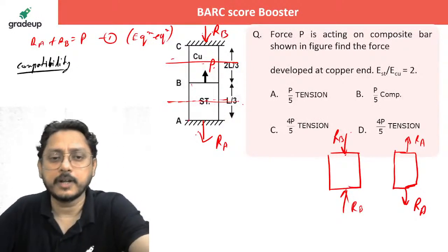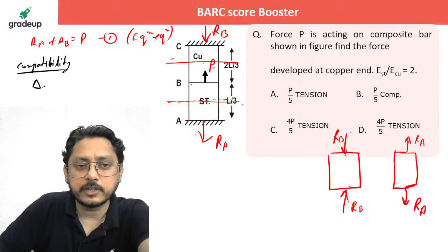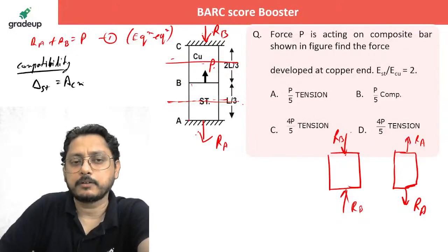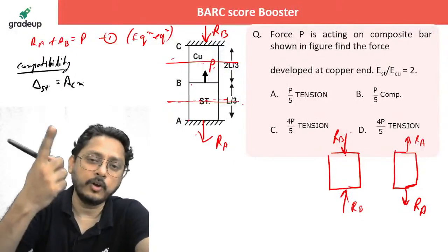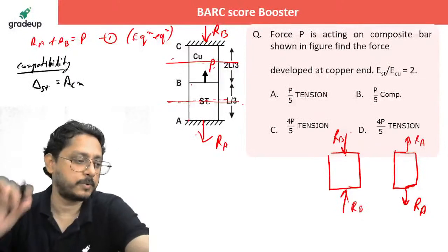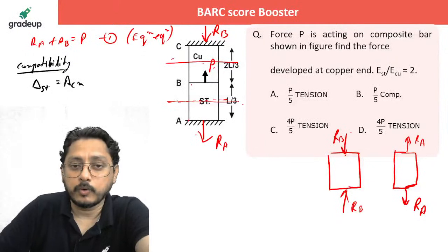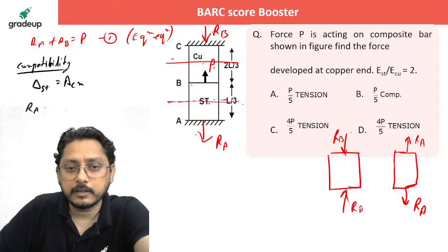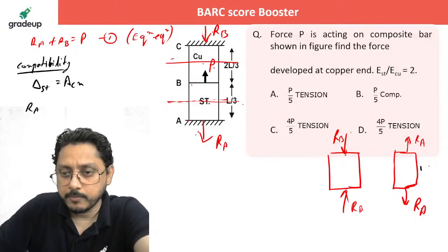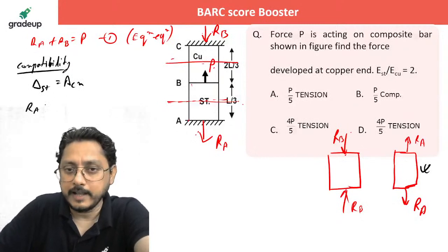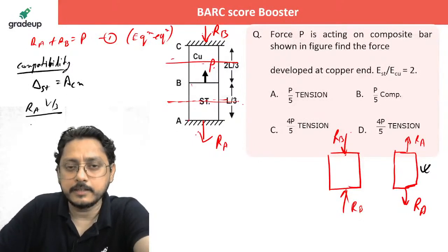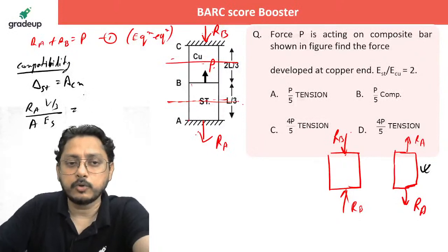What are the compatibility conditions we have? The delta in steel must be equal to the delta in copper. Or I should say, elongation in steel and contraction in copper must sum to zero. So delta in steel is PL by AE. Now what is that? RA, as you can see from the free body diagram, PL. What is the length here? L by AE. A is the same, but E is different. E of steel must be equal to...